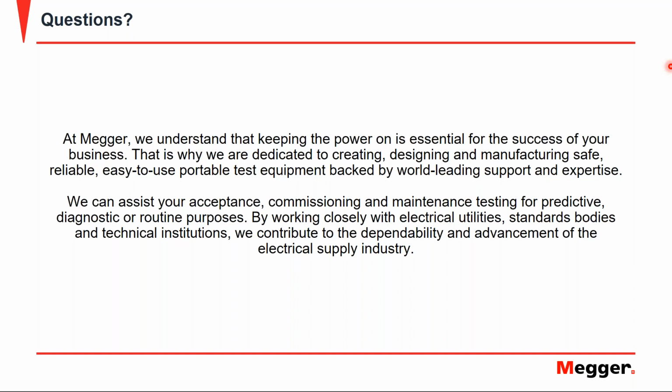So that way, again, you can determine and grade the severity of the degradation in your cable insulation and help to determine what cables need to be replaced at what time. So I wouldn't necessarily say better, though it does offer the strong advantage of being able to determine your inception and extinction voltages. But there are also certain advantages to doing online testing and online monitoring, of course.